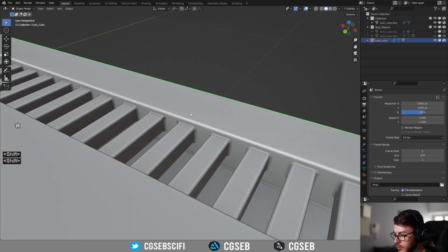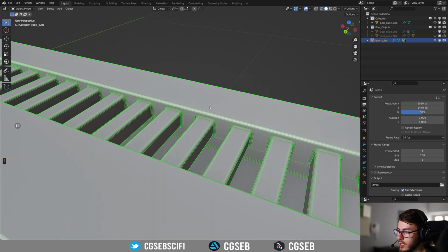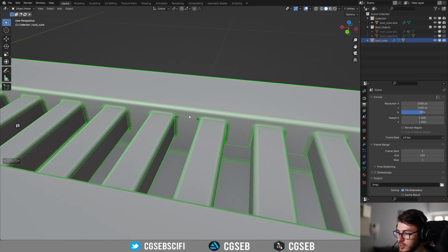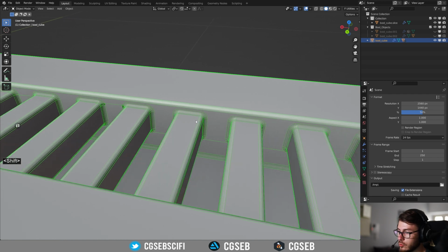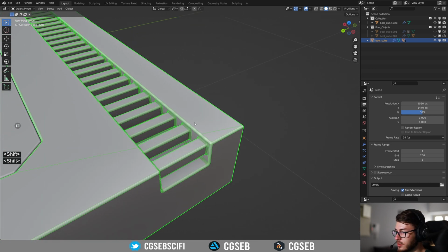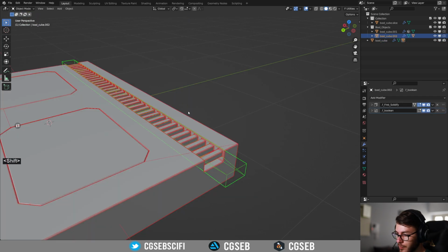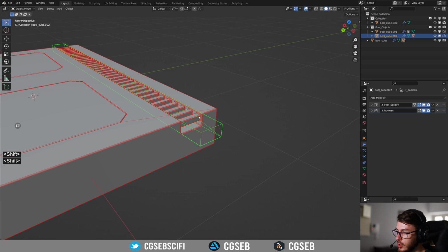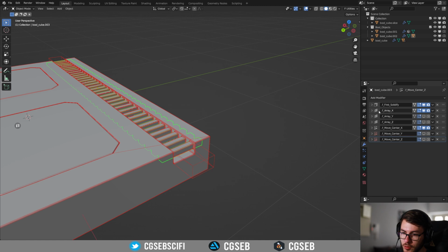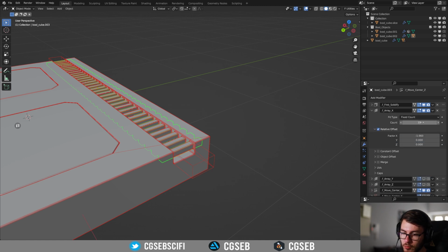To fix them, remember, just show the wireframe to try to understand what the problem is, and most of the time it is because Blender is adding edges over there and over there to support the mesh. And we need to help Blender understand where to put those edges. So to fix this issue, you're going to select this and go here to Array and check the count that you have. For me, it's 35.